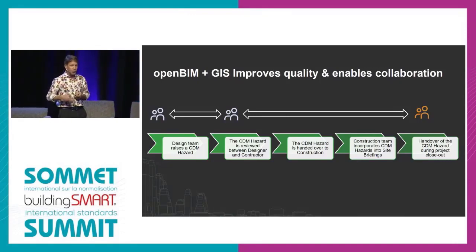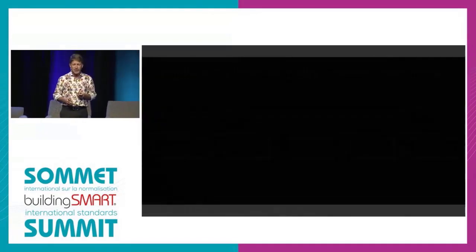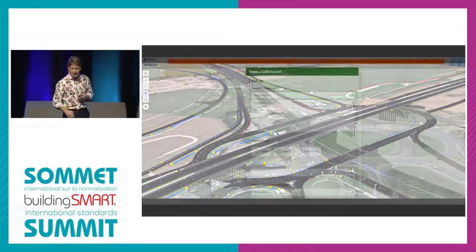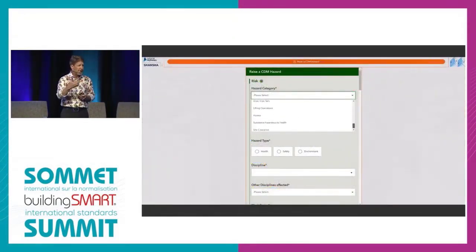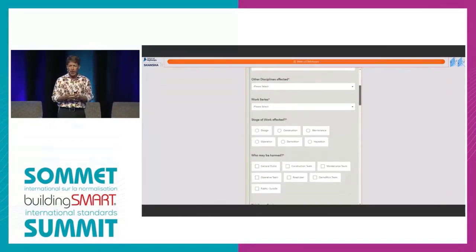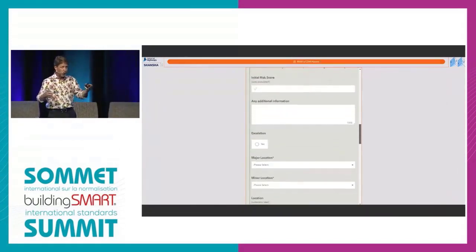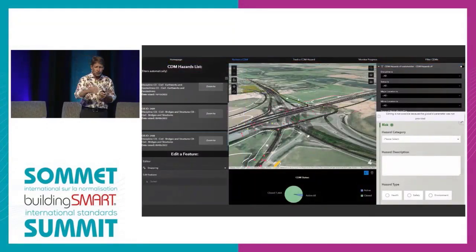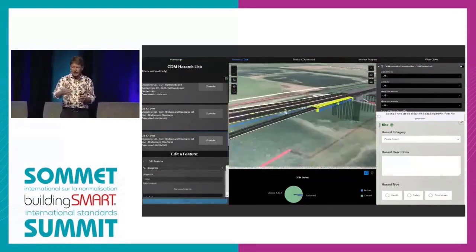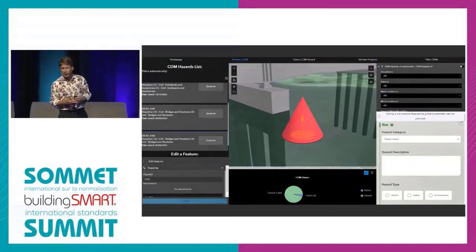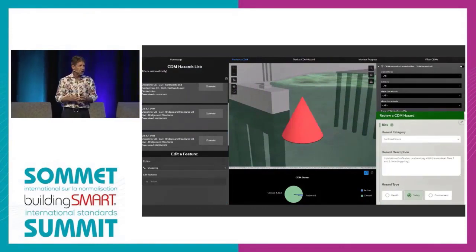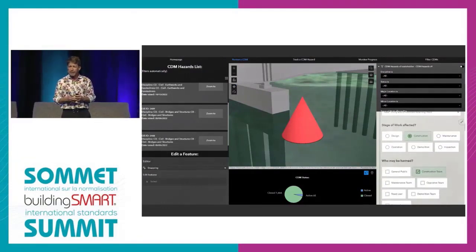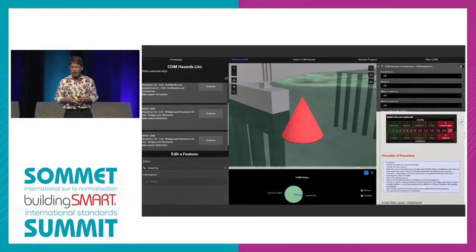So the way they've gone about addressing this workflow with technology is they've built out a solution for this rather complex interchange, a mobile device that uses Survey123, an Esri product, a completely customizable, no code, zero code form application that they capture the conditions, then visualize them on a desktop in a browser-like view. This is using another low-code tool called Experience Builder, where they can zero in on any of those conditions that were identified, view them with more context, see all the properties that were collected out in the field, understand the situation before they start construction.